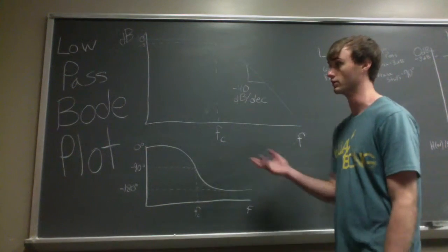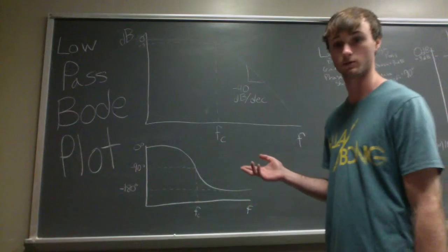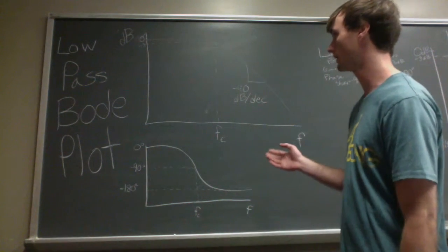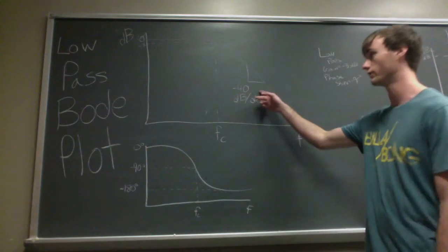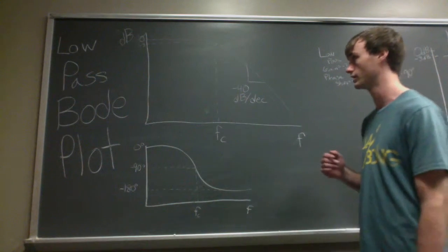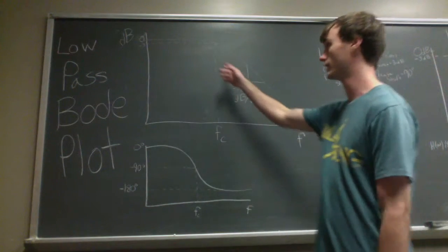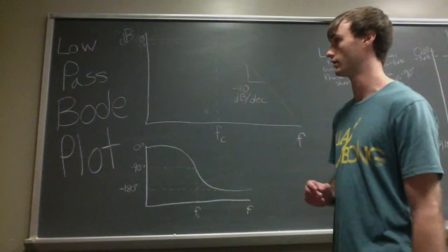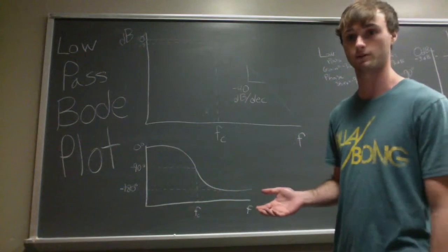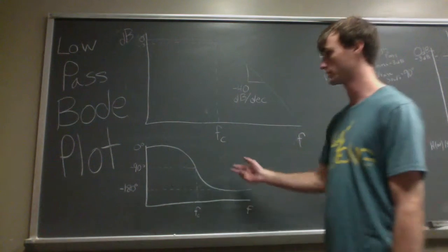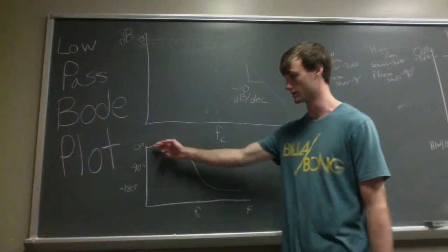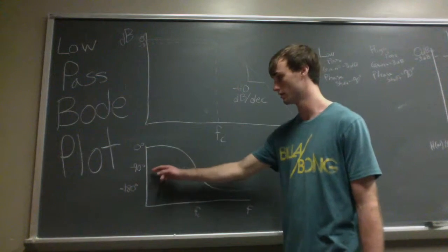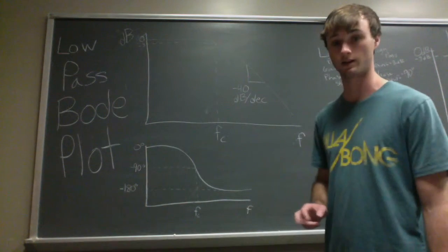Here we observe the low-pass Bode plot for the second order low-pass active Butterworth filter. Here we're observed to have a roll-off of -40 dB per decade and also have a -3 dB gain on the low-pass filter, just like the high-pass filter. We observe the phase shift to start at 0 and to run through -180 degrees with its phase shift angle at -90 degrees.